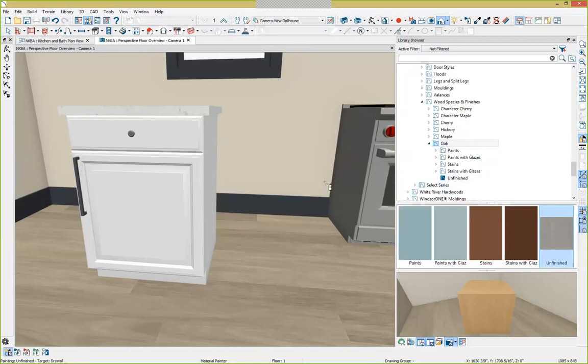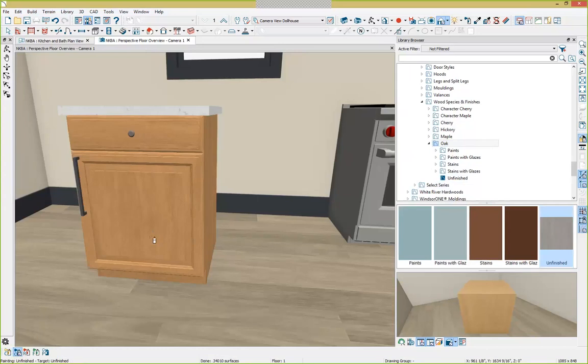It updates to a little spray can indicating that I can apply this material in the plan. And in the bottom left-hand corner, there's different scoping modes for distributing this material. I'm going to change it to be object-wide so that when we click on the cabinet, we're going to update this white material on the entire cabinet. And there we've got our oak material applied on the cabinet.